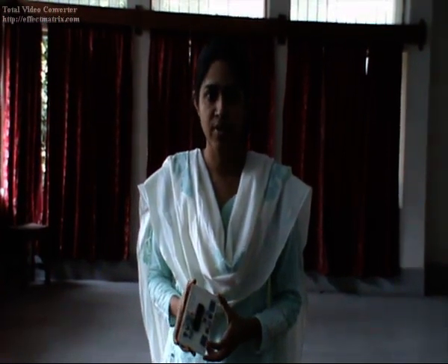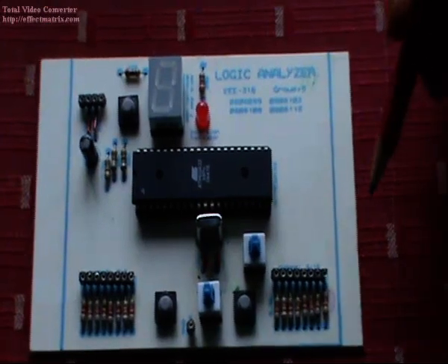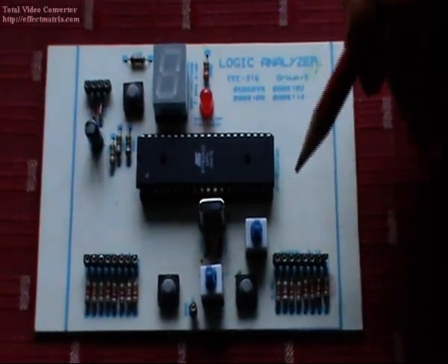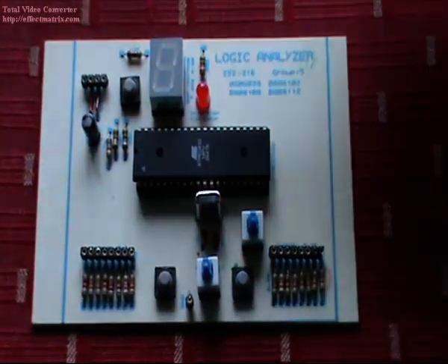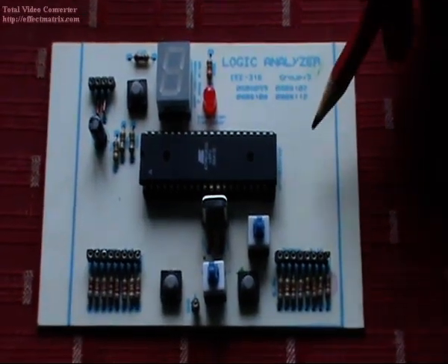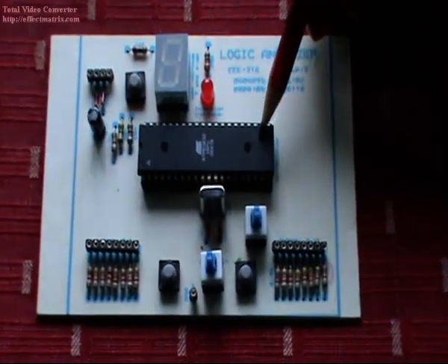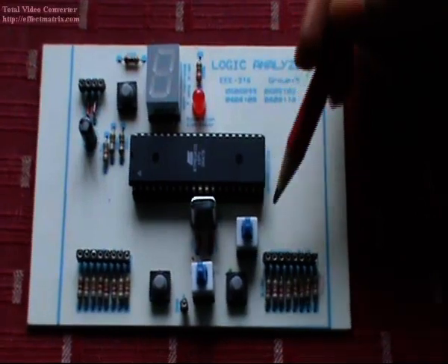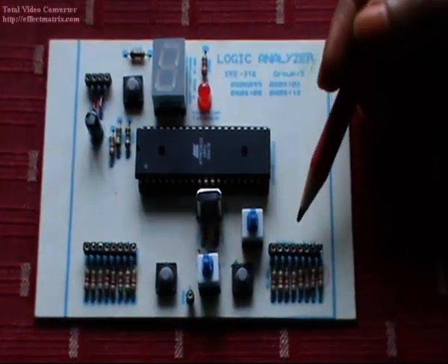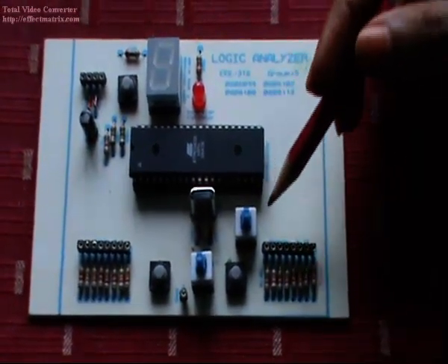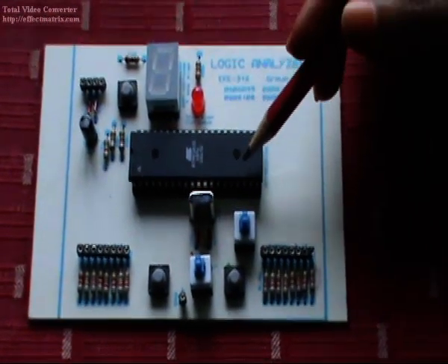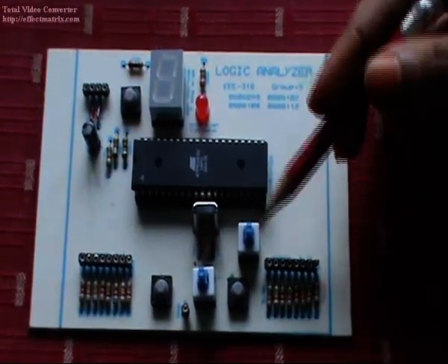In designing any circuit with switches, an important concern is pull-up or pull-down resistance. Where there is a switch, there should be a resistance with it. In our circuit, we haven't used any such resistance with these switches. Rather, we have activated the internal pull-up resistance of this microcontroller, and by doing this, we have managed to make our circuit simpler. When the switches are unpressed, the connected pins are high, and when the switches are pressed, they become low.